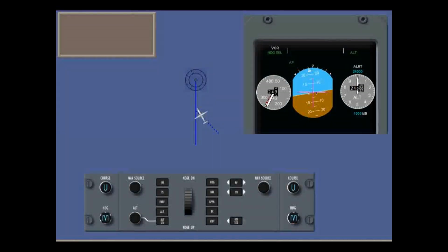Timing of the capture depends upon heading speed and angle. The aircraft banks, and the EHSI deviation bar starts to center. And within 2 dots on the deviation scale, the capture maneuver starts. The mode is VOR capture, with the change highlighted. When stabilized, tracking the VOR radial, the star disappears, again with temporary reverse video to get your attention.